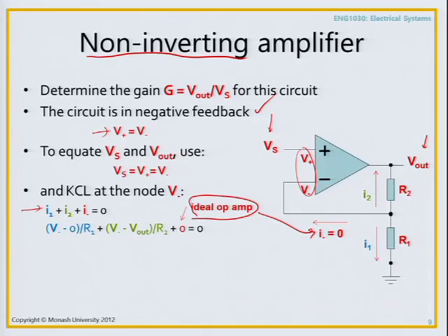Now this makes things really easy because now you see why I had to show you the rule before about how to calculate currents from voltages. Well, I1 is just V minus, subtract 0, so here's 0 volts because it's connected to ground, divided by R1, right?